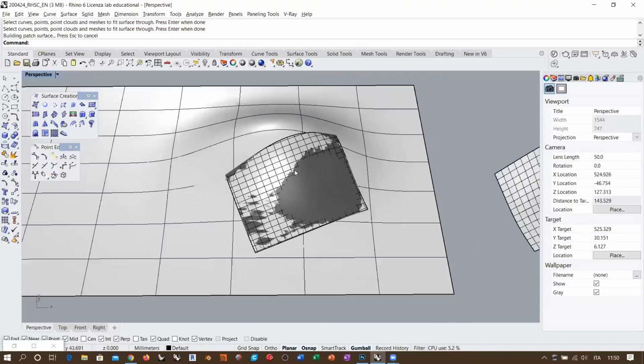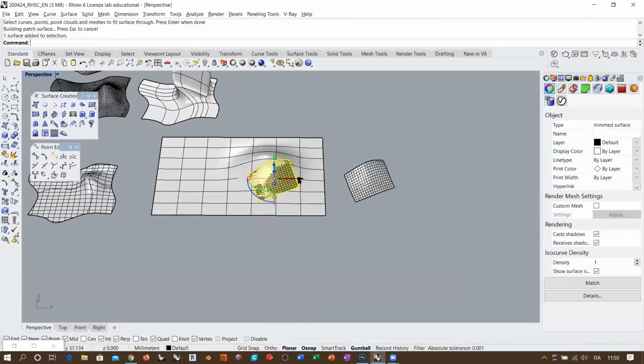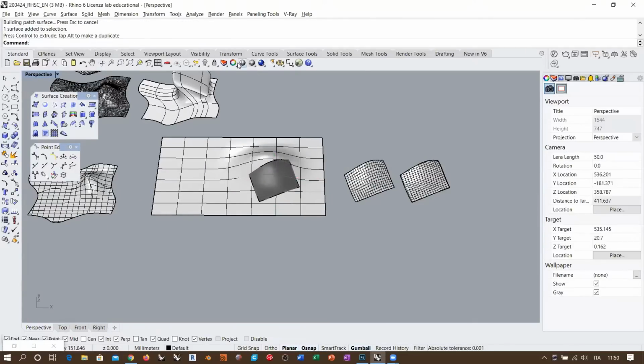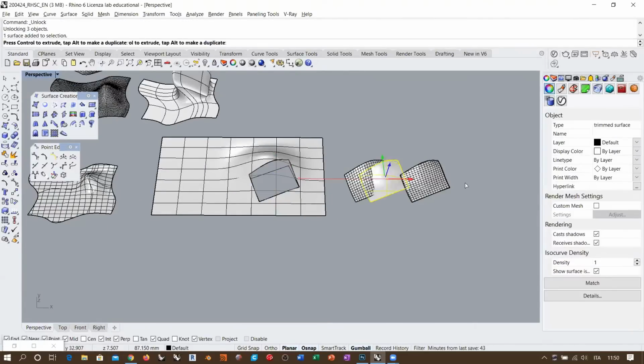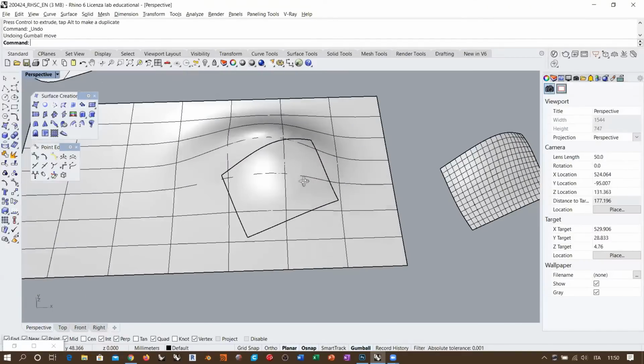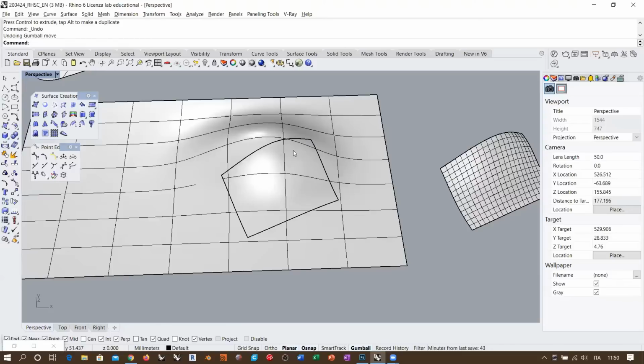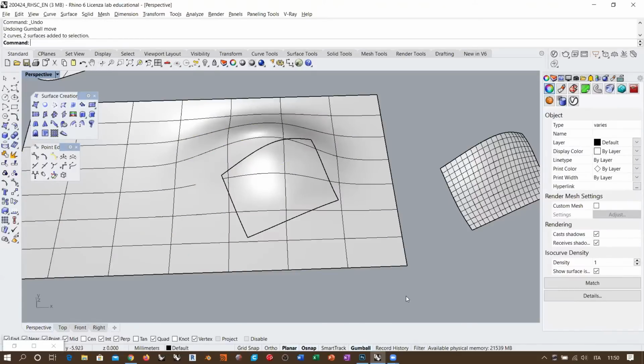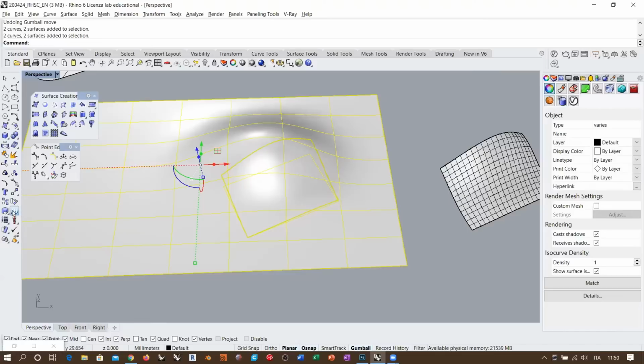But even in this case, for example, this is the patch surface, and this is the patch surface with topology adapted to the surrounding surface. If I consider these objects here, I might also make some curvature consideration. I'm not going to use the zebra analysis right now because it's less precise. I want a more precise analysis. So I go here and perform some curvature analysis,